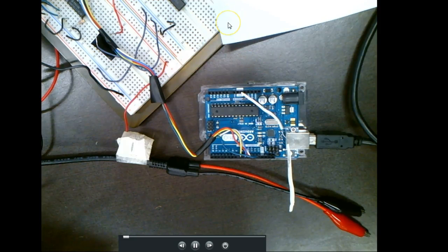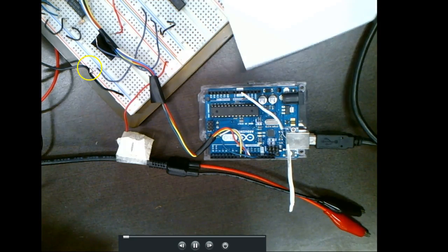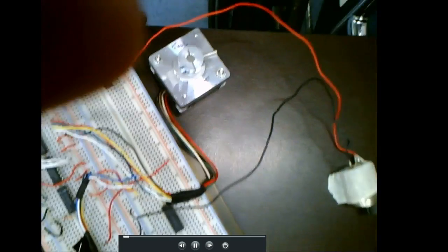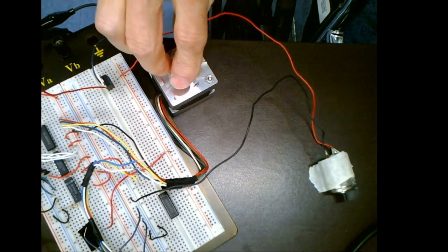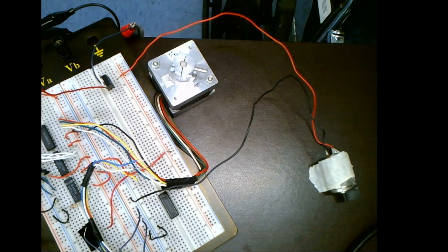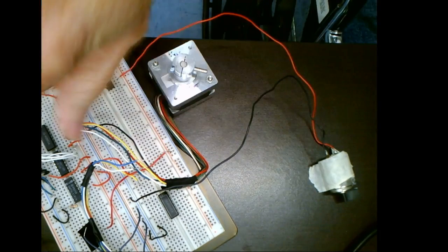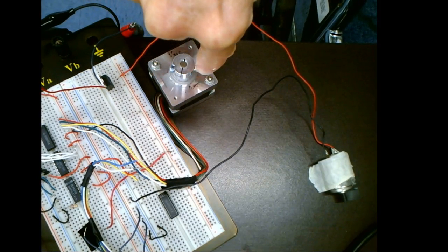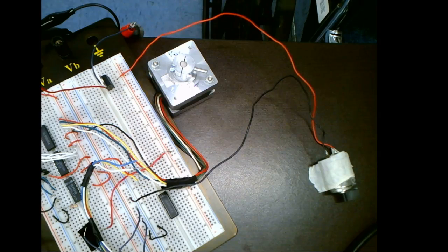So what this is right here is a special motor that we call a stepping motor, which we'll talk about next class. What this thing does is it moves in steps, which is pretty neat. This is a 100-step motor, so if I send it 100 steps, it would go exactly one revolution, and then it would stop.